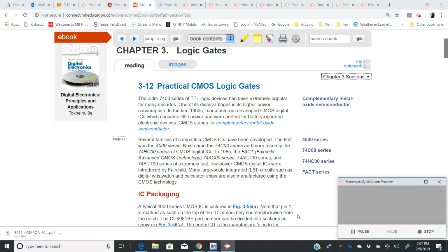Finally, CMOS. You have to understand CMOS itself is static sensitive, and it's because of its construction. And they're much better than TTL, and they're more expensive. But TTL, more expensive, CMOS, less expensive, but CMOS itself is static sensitive. Both are really static sensitive, but this one really is. So even if you don't think you have any static electricity, you hit those pins, you can actually do some destruction inside the integrated circuit. So just keep that in mind.